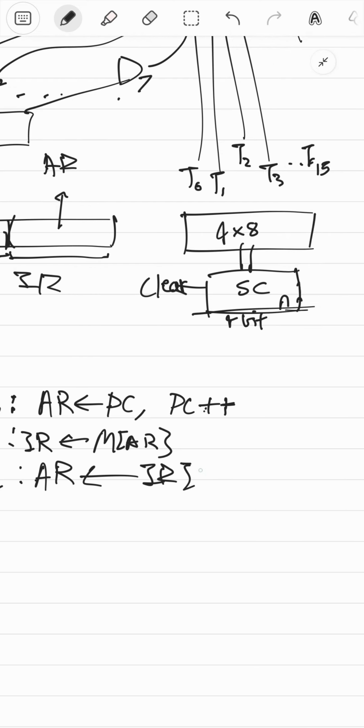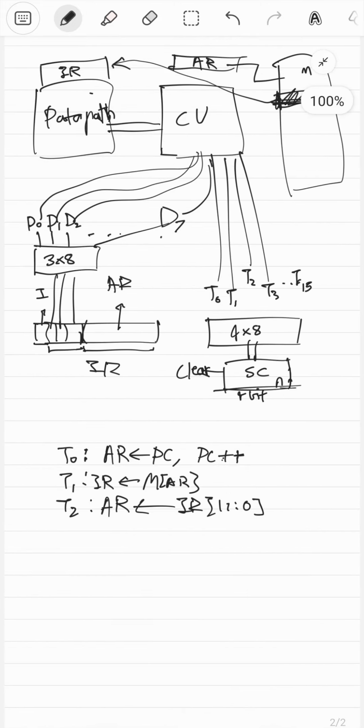So all the first 12 least significant bits, so 0 till 12, or okay, in Verilog style this would be 11 down to 0. Yeah, okay, this makes sense. So this is the stuff that happens every time you run an instruction. This processor just keeps doing this over and over and over again.